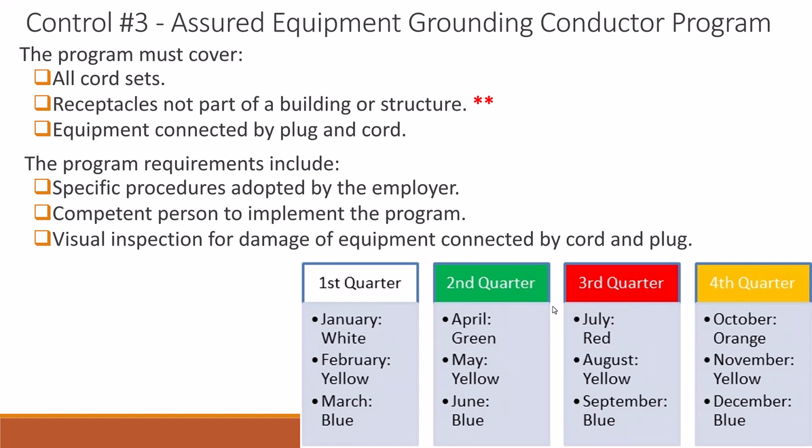So what they do is they use a system like you see down here at the bottom, where they could have a quarterly system where every quarter you test every piece of equipment. And so they'll use color codes, because they typically will take some white electrical tape and tape it around the shaft of the drill cord so that you see that white color and you know it's been tested that quarter. And then if not, then you don't use it.